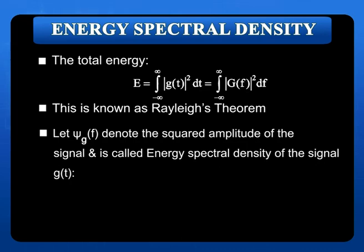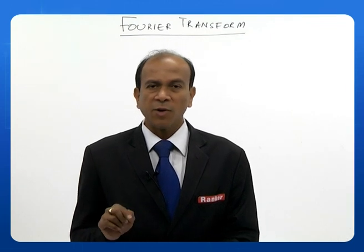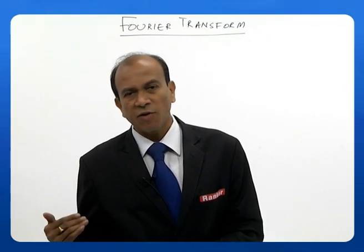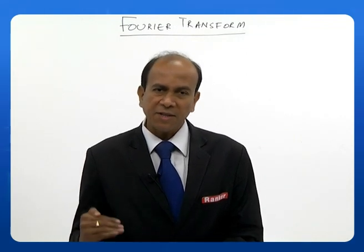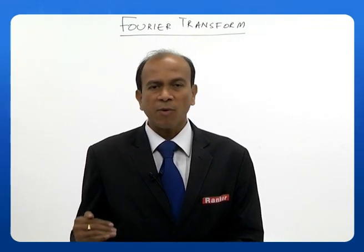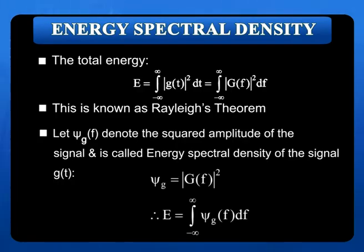Let us summarize this. Now you know the energy of a signal is given by the integral from minus infinity to plus infinity of mod g of t whole square dt. So when I calculate g of f, the Fourier transform of g of t, the energy will be equal to the integral from minus infinity to plus infinity of mod g of f whole square df. Now let us use psi g of f is equal to mod g of f whole square. Then this psi g of f is called the energy spectral density.